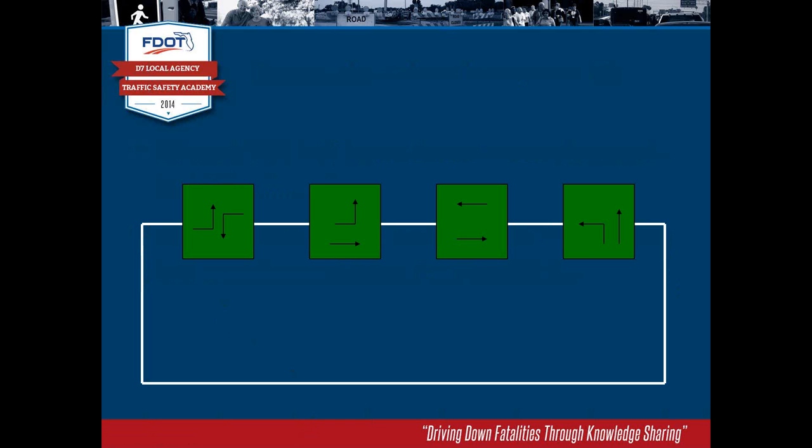Well, we said we had both eastbound and westbound left turns having some demand, so they're being detected. Again, it doesn't matter, loop detection, video detection, whatever. So the eastbound and westbound lefts will start up. The lighter direction will gap out, and so again, the eastbound left will continue.